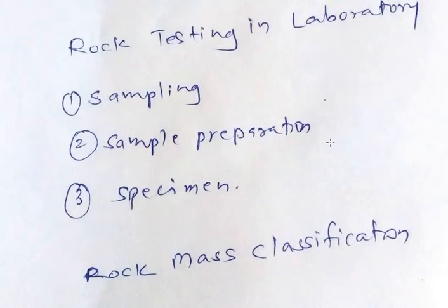Blasting should be avoided before drilling. Cracks developed due to blasting in core may mislead the result. Diamond drilling should be used to take samples from greater depth. Collected samples should be marked on the map to indicate their original position and orientation.